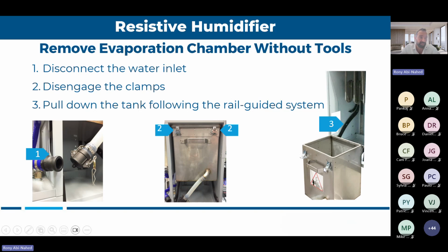So keep in mind, if you're designing any precision electric humidifier, you always need to have an RO before the unit, have a resistive unit with SCR control, and definitely you need to also have a humidistat that can be precise. Because I've seen some engineers design stuff around it, but they end up with a range of humidistat that cannot give you precision. So the whole system should be designed for precision, not just the unit itself.